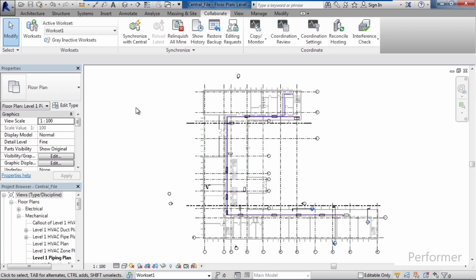So as a review, in this lesson, we covered work sharing. We talked about what work sharing is and how it works. Well, work sharing is the way to create a central file that all users can synchronize changes to while working on their local copy of this project. The central file can be divided into work sets based on function or discipline of what the users do, such as mechanical, electrical, and plumbing, or more specifically, HVAC, electrical, piping, tubing, or architectural elements: doors, windows, and walls.